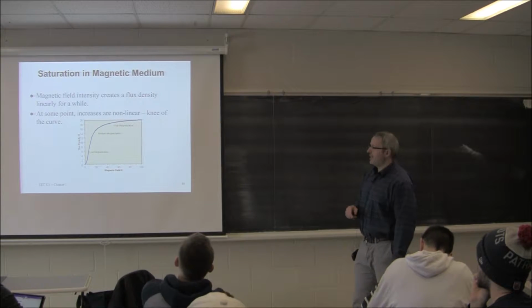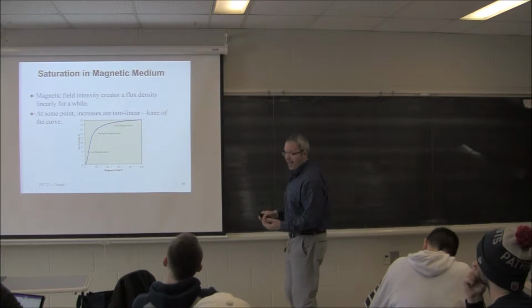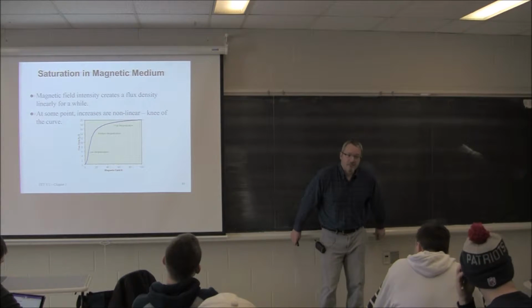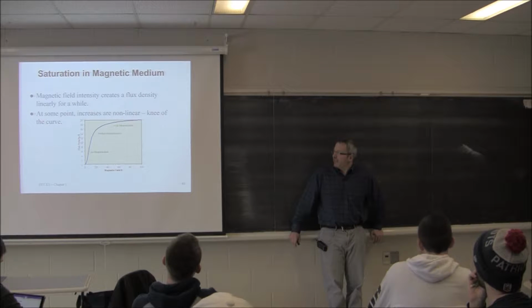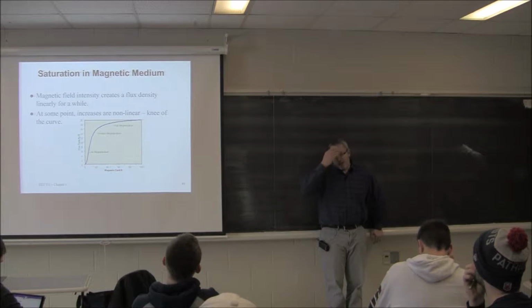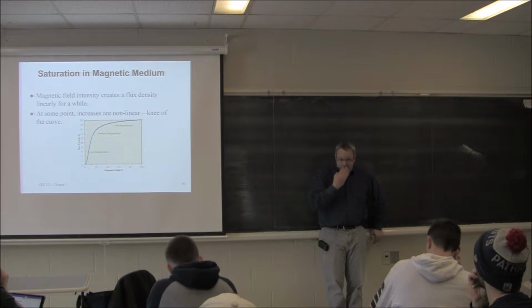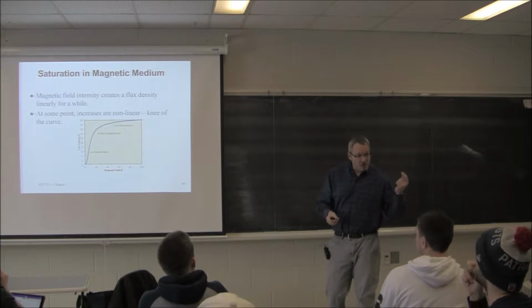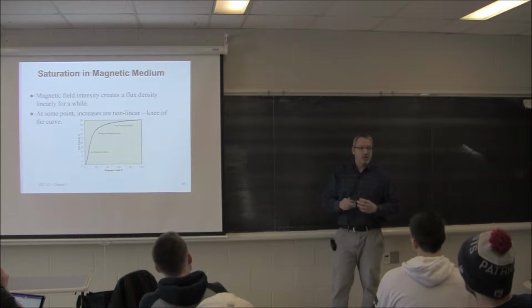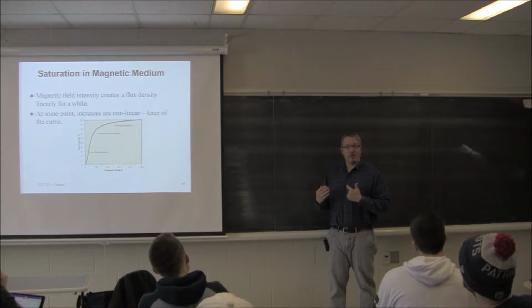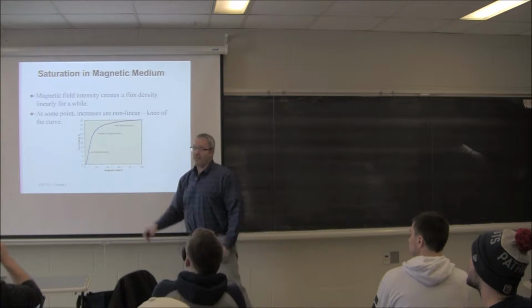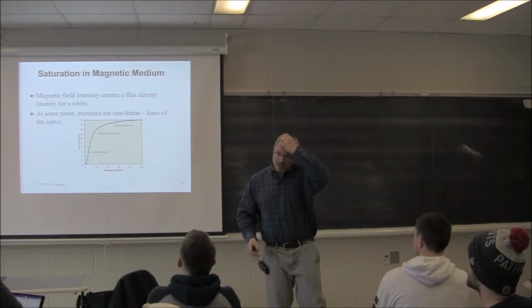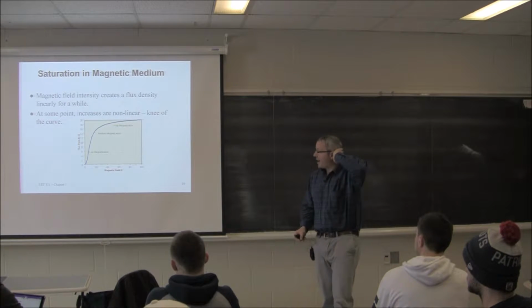And the reason why we have to come back to that problem is based on the fact that magnets aren't all that good of a magnetic conductor. We talked about how some of the world's best magnets are only 50,000 times more magnetically conductive than air. The same thing would also apply to electric circuits if we were not concerned about heating them up, and that's that they would get saturated, right? If you keep pushing electrons through a piece of wire, you can only push so much before the resistance starts to build up. That's the concept of saturation. So it's much more prevalent in magnetic circuits because, again, the conductors that we have are very poor for magnets.